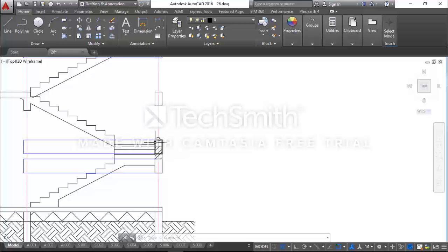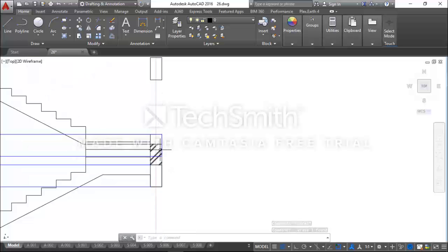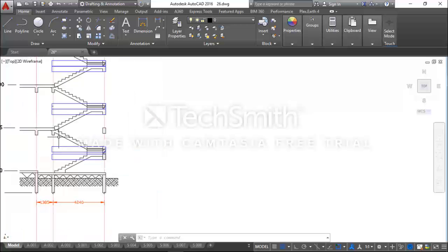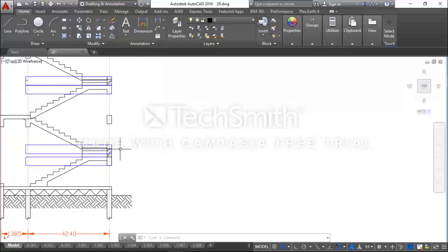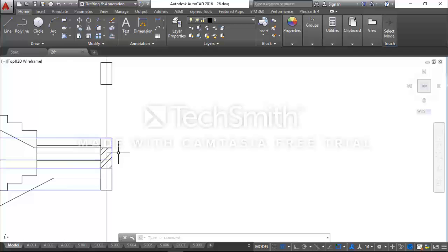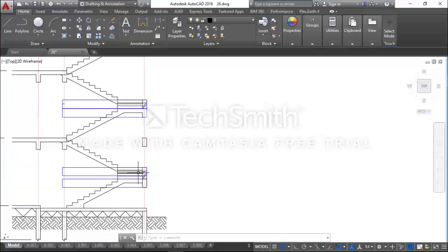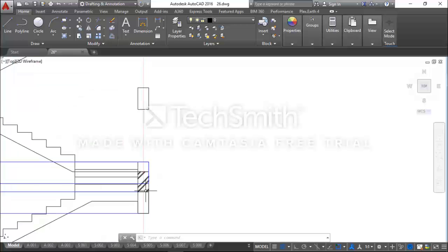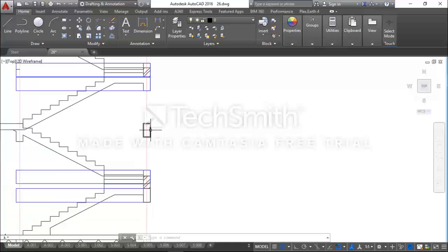Okay, no, I only position one beam there. I'm not positioning two beams because it's not economical. It's not wise. I will select this and delete it. Remember, I told you that we'll place a beam here, and we'll build a block wall on the beam, and our third flight landing will sit on the block wall. That's what I told you when we were drawing this general arrangement drawing. So this is our beam. We want to lower the beam from this position to this level.